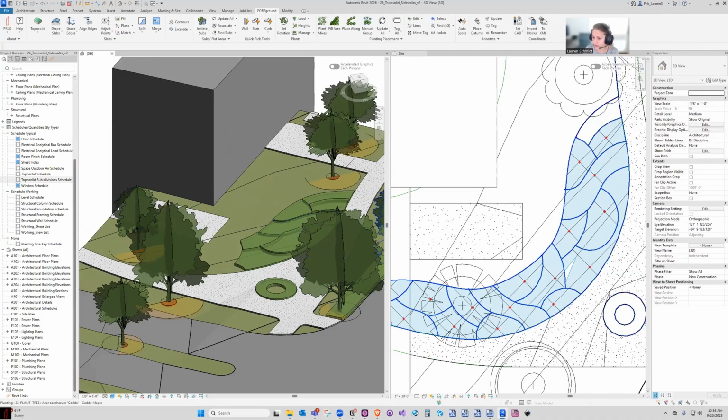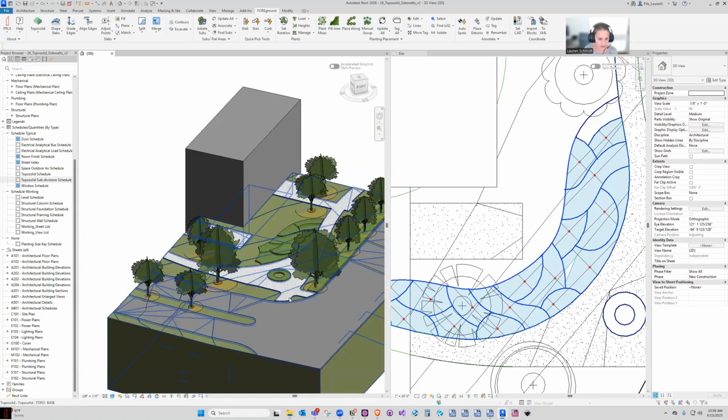Okay, so that is excavate, set contours. One thing I will point out about excavate is that just because you can cut and excavate all your topo solids now and all of your subdivisions doesn't necessarily mean you should. And sometimes you can't. You're definitely going to have instances where your subdivisions will fail. I was testing this one, and I think when I recreated it with new to get the contour lines, it failed.